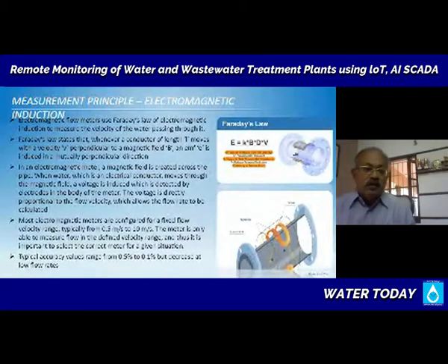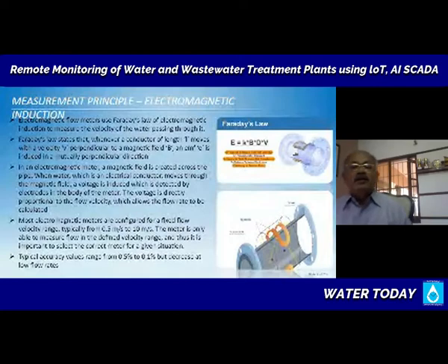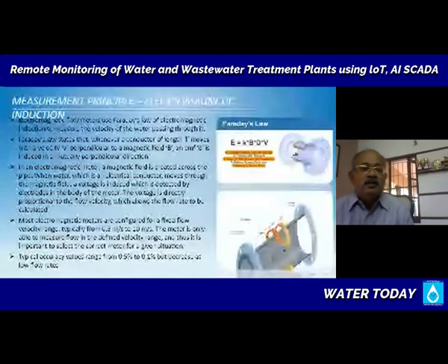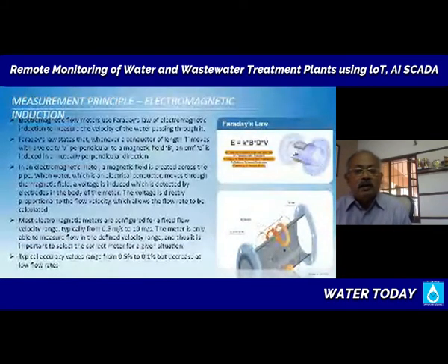Now, of course, the thing to note here, as we discussed earlier, is that the velocity of flow should be above a minimum cutoff, for example, 0.5 meter per second. Above that, the meter will work efficiently. Otherwise, it does not induce an EMF accurately at very low velocity, and hence the meter accuracy suffers considerably. Accuracies vary from 0.5 to 1%, and once this is working, it can be a very, very rugged, robust measurement device, a long-lasting device as well. But the trick is to make sure that magnetic flow meters are deployed only where it matters, not everywhere. It's not a one-size-fits-all type of solution.